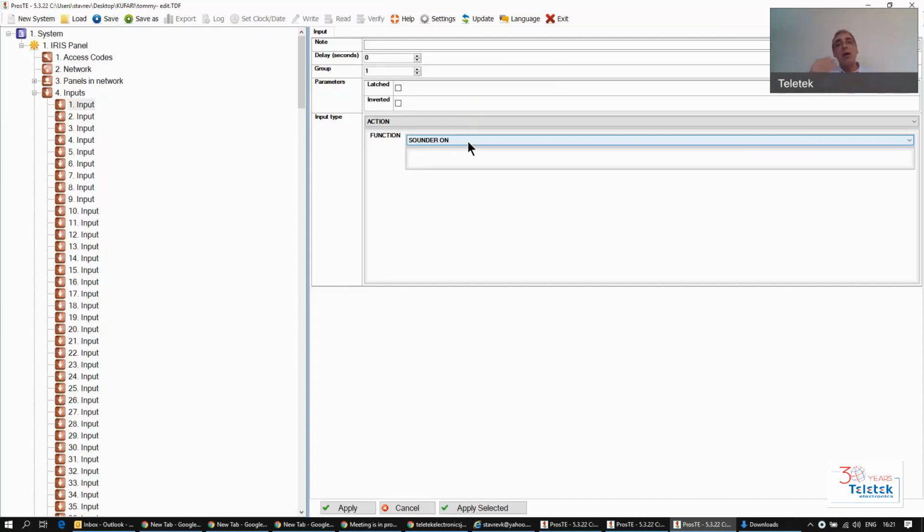This is when you want to activate some relays to send elevators down, open doors, fire escape doors, or other bells or whatever. You don't want to activate them before that. That's why I'm saying sounders on is probably one of the most used logical inputs that you can create, an input that monitors the sounders. In case the sounders go on, then you can trigger different events or different modules in the system. So let's say I'm going to go through the process of designing an input.